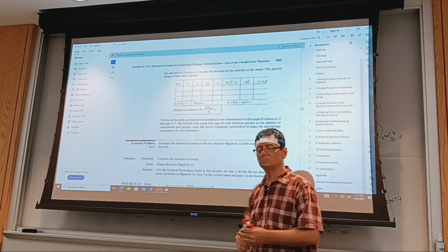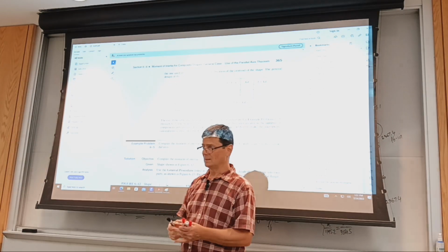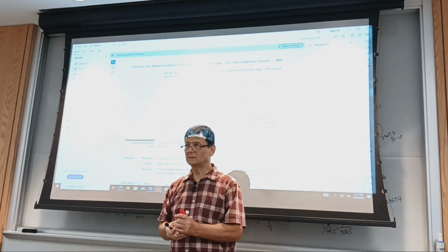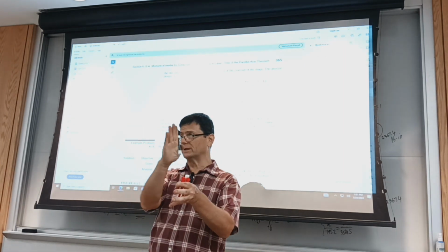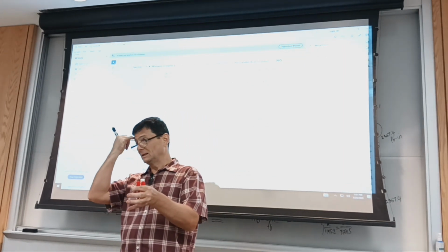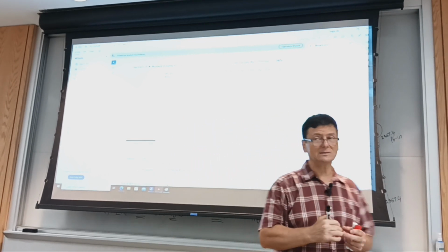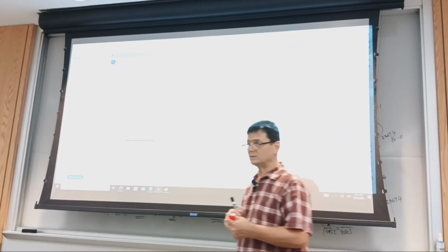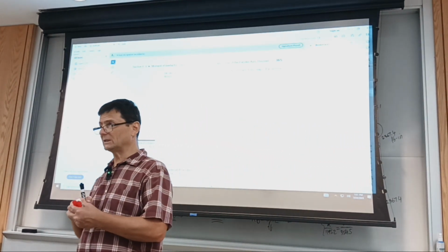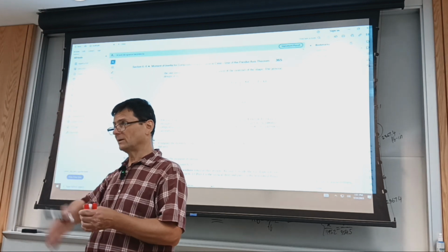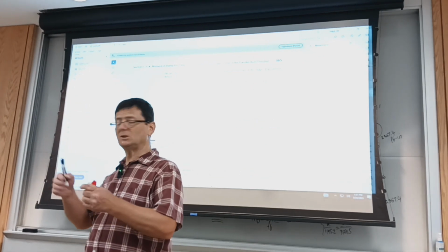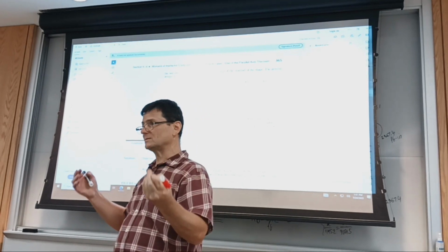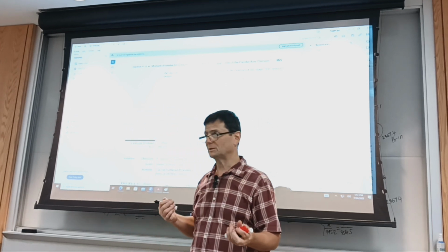All right, you see only y here. Why is that? Because it's not of interest to us to know where the centroid is on the horizontal axis, or maybe it is, because later in the chapter, in the next chapter, which is 7, we discuss loading of shapes that don't have vertical symmetry. And as you load a piece, you don't want to induce twisting with bending. That's a useless additional stressing of the part, if it makes sense.